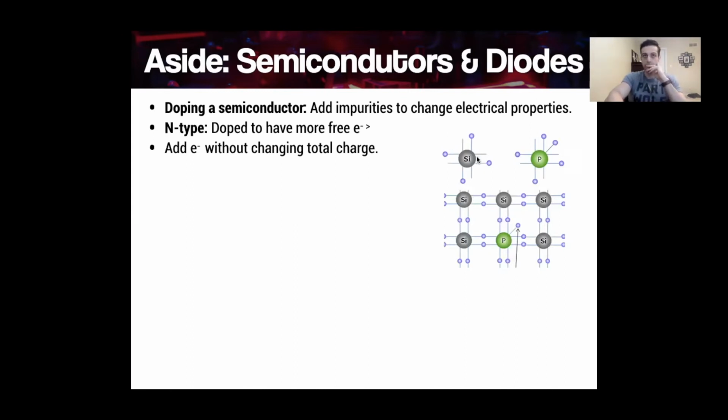So we have all the silicon lined up, and it's like a puzzle piece here. If you slide these together, they'll line up and create covalent bonds, and then the two silicons will share these two electrons. It would just be a bunch of silicons connected together with pairs of electrons. Now you put a phosphorus in and it has an extra valence electron. So when it creates a bond with the silicon, it is now a positive ion inside of the semiconductor, with a valence electron floating around it and through the semiconductor.